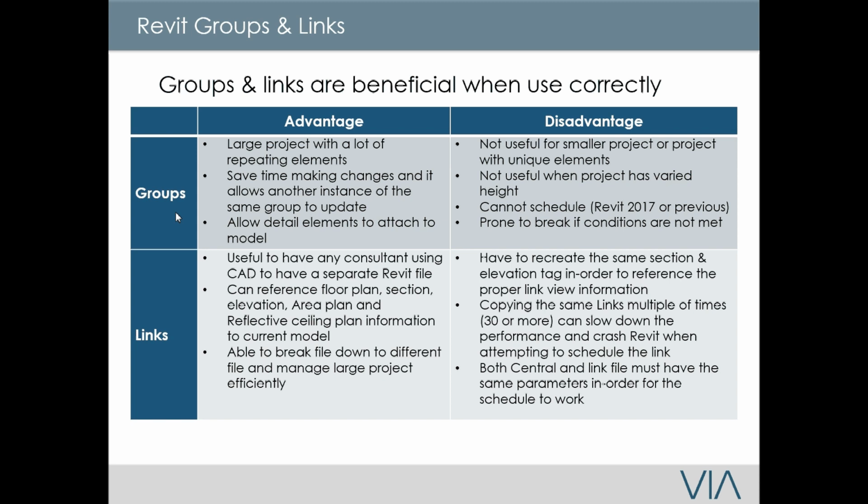For links, the nicest thing is that you can reference them. What I typically like to use it for is if you have consultants that are still using AutoCAD, you can create its own separate Revit link, and then you can link all the CADs into that file.